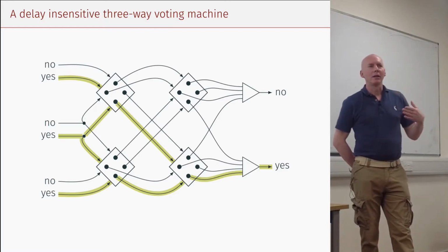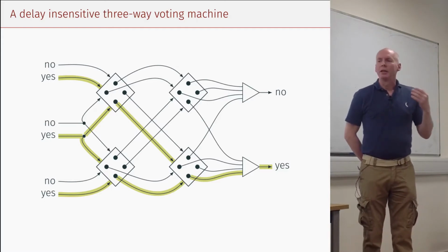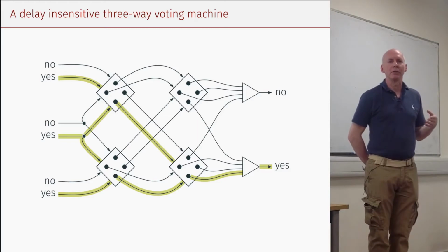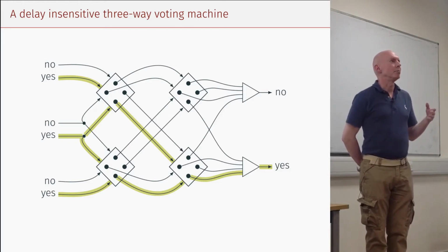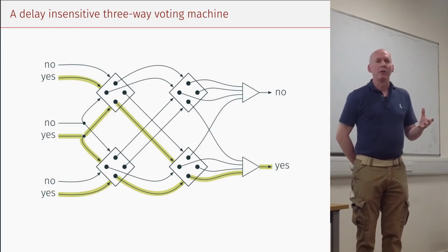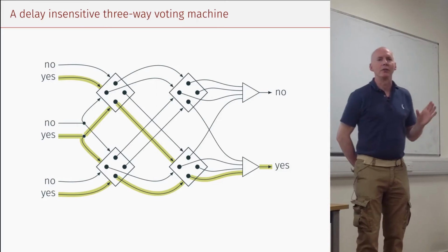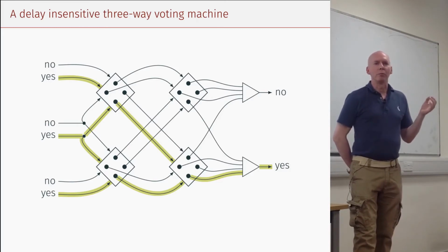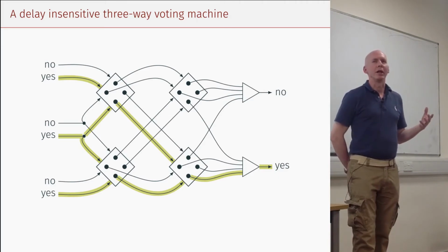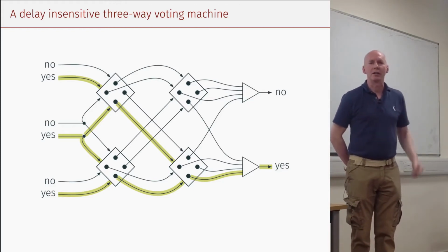Well, if you take the cost of state-based synthesis to be a constant, I believe that the cost of doing the Petri net model, which is the only other thing, can be done more or less linearly in the length of the specification. It may be possible to construct an adversarial example where you have a transition or a monitor inside it whose state space turns out to be bigger than the overall circuit, but I can't think of how you would do that, because the monitor increases only in proportion to the number of transitions it's interacting with, not the whole specification you started with, if you know what I'm saying. But I guess somebody who's better at that kind of stuff than I am could probably do a proper job of the exact algorithmic complexity analysis.